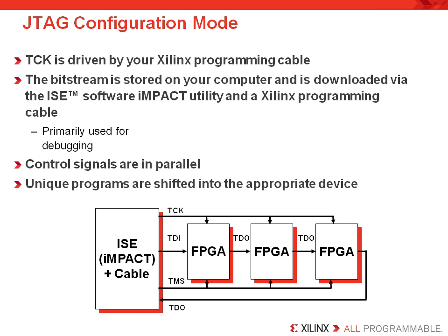Since reconfiguring in this mode does not require any memory components to store the bitstream, this mode is primarily used for debugging and not for the end use of an application. This flow is possible because Xilinx FPGAs are SRAM-based and thus reprogrammable. This means that the user only has to generate a new bitstream with the iMPACT utility and then re-download the new design into the FPGA.